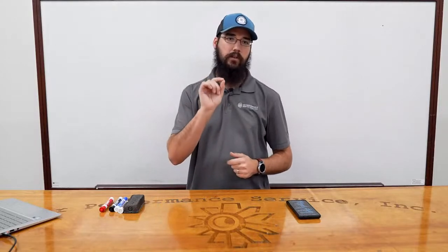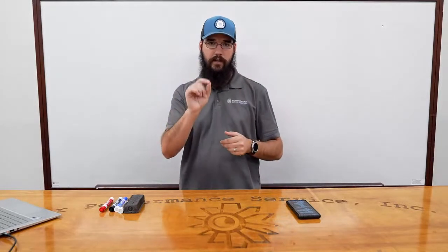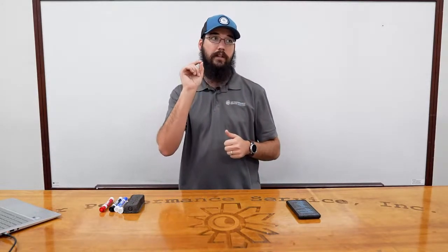I do want to make a distinction: RTUs and splits versus some of our larger systems like a self-contained or an IntelliPack or a 50N series for a Carrier RTU, even a Voyager for that matter. Those would be what I would consider a high static system. Now, I do want to clarify, I'm speaking in a very narrow field of view. When I say high static, it's not what the industry means. If you talk to an engineer and say, hey, we're working on a high static system, what I'm saying right now and what he's going to feed back to you is not actually the same.